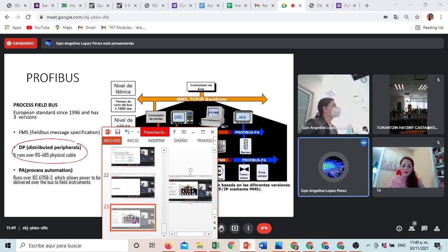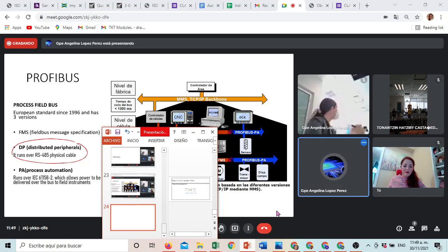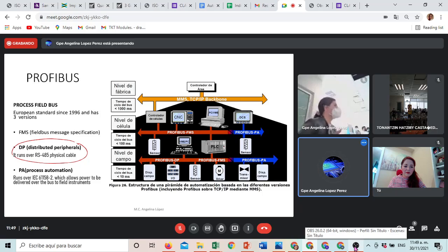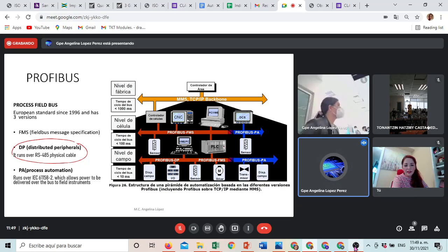The ones that we are using here are very simple. They give me 1 or 0 if they are active or not. But there are some other devices, proportional valves and others that we'll see in the 5th quarter when we see advanced PLCs, that cannot be connected directly to an I/O module. I need a specific module to connect them to the PLC.